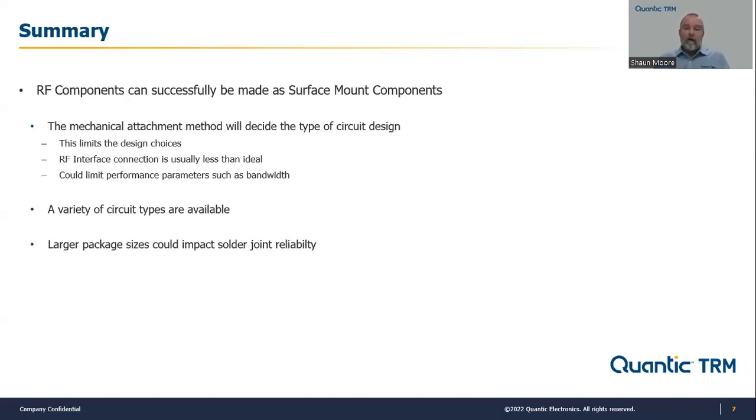Certainly. So, most components can be made surface mount. There are various things that we need to look at as we're translating the more traditional technology into a surface mount kind of package. There are limitations that we do need to consider, whether or not some of those considerations are strictly manufacturing yield issues, whether we're dealing with going to a slightly different circuit layout, as well as a different packaging layout.